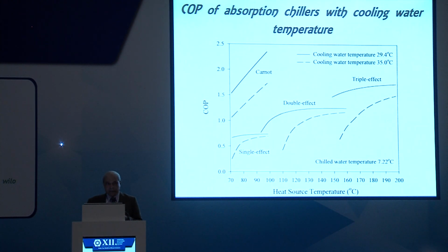Less efficient as in lower COP. But of course, at lower temperatures for the evaporator, the quality of cooling is higher. The quality of cooling is higher as in you get lower temperature cooling, which is a good thing. But you get it at a lower efficiency.